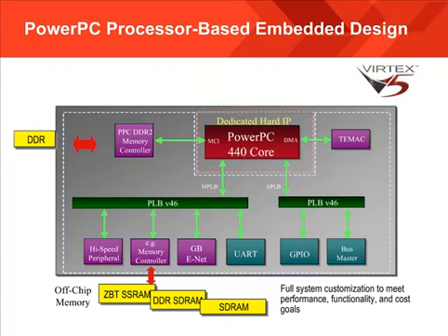The PowerPC 440 also has a memory controller interface or MCI port, and it's designed to connect directly to the PowerPC processor's DDR2 memory controller. The separate memory interface improves system performance and enables access to a large memory. The PowerPC also has 4 direct memory access or DMA ports. These are commonly used to connect to the tri-mode Ethernet MAC included with the Virtex 5 FPGA families. And again, these are dedicated in silicon in most of our FPGA families.